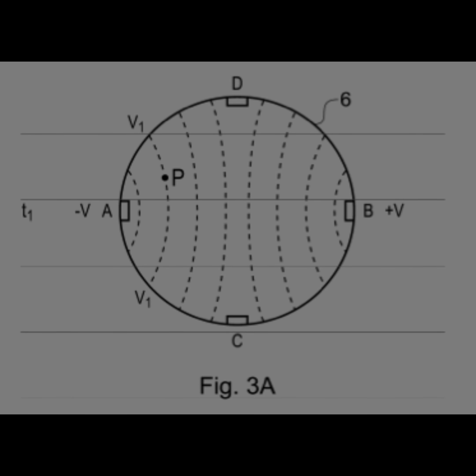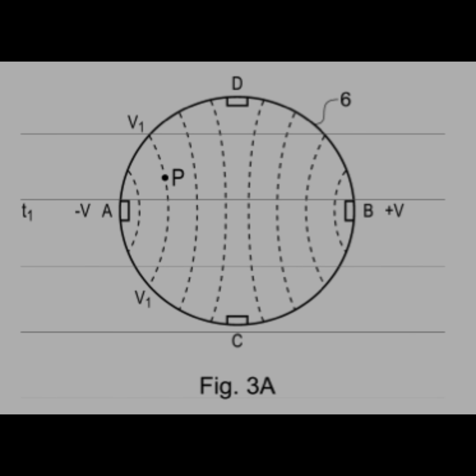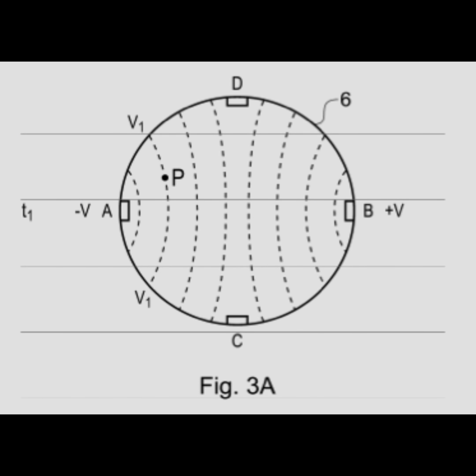Document D1 discloses a prior art joystick. It comprises an actuator and a hollow, hemispherical, and electrically insulating support on which a resistive layer is arranged. The resistive layer is a band in the form of a spiral. The resistive layer is connected to a voltage supply via contacts at the ends of the band. The voltage varies linearly along the band with distance to either of the contacts.